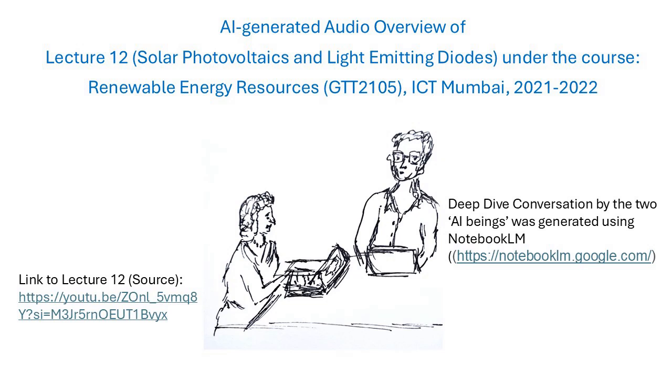Wow. Why aren't all panels multi-junction then? Mostly cost and complexity. They're significantly more expensive to manufacture. So they're primarily used in specialized applications where high efficiency is absolutely critical and cost is less of a constraint, like powering satellites in space. Okay. Trade-offs. Always trade-offs. And it's also worth remembering that there's often a trade-off between achieving maximum efficiency and ensuring long-term stability and durability. Silicon, while maybe not the absolute efficiency champion, is remarkably stable and durable. It lasts a long time out in the elements. Right, which is crucial for a decades-long investment like a solar panel.